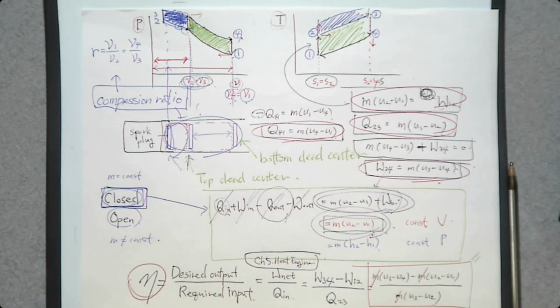And that's how we came up with the idea of the diesel cycle. Because if you just keep increasing the compression ratio, the air-fuel mixture is going to self-ignite before the piston reaches the top dead center. So instead of compressing an air-fuel mixture, let's compress only air and then inject fuel later. That is the diesel cycle, trying to increase this compression ratio, because there's a limit for the compression ratio in the Otto cycle because of this spark plug. Okay? So that's everything for the Otto cycle.